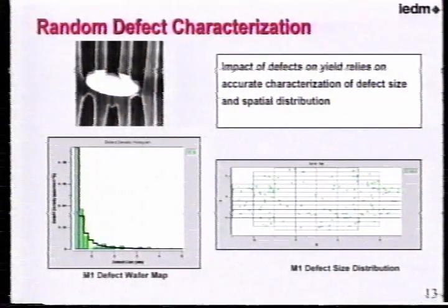How do you get rid of them? So you have to first of all characterize this to find out what your impact on yield is. For example, if your critical area is such that the defects below this size do not impact you, no point working on them. However, in the next generation, they will become important. The spatial density tells you about the footprint of the equipment, where it is coming from, etc. So it's very important to know both the spatial as well as the size density.